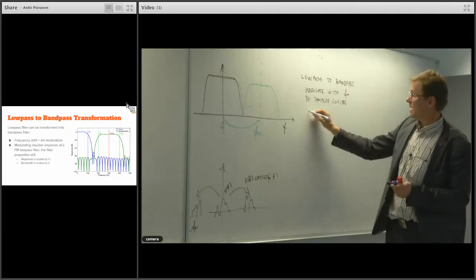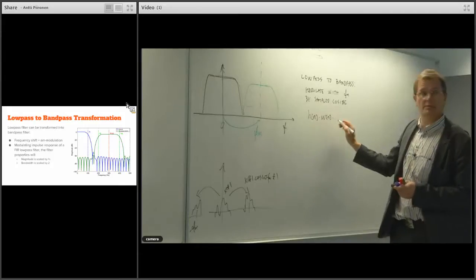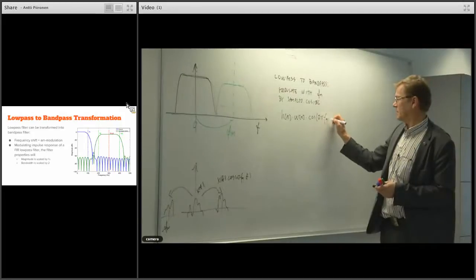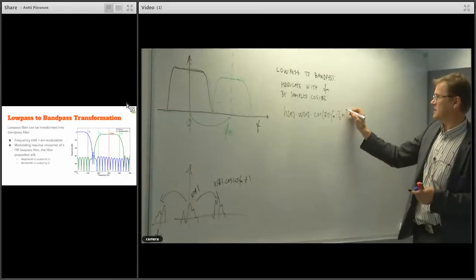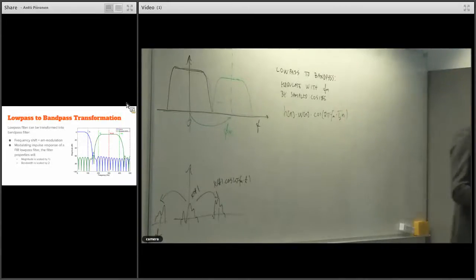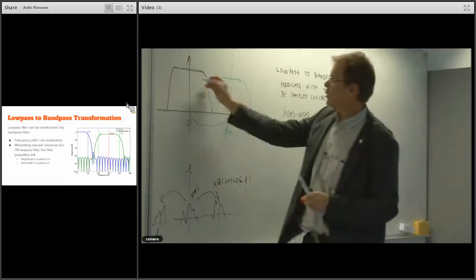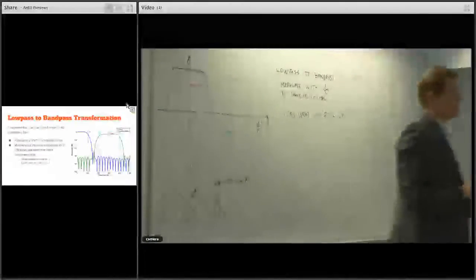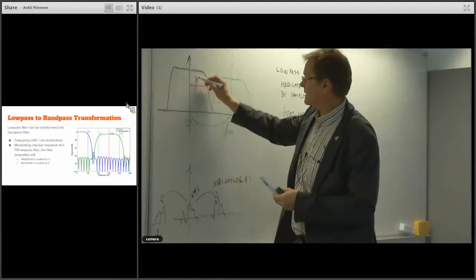Okay, so we have h of n times the window shape times cosine 2 pi fm times t s times n. Okay, that's the whole thing. Just with one reminder about bandwidth. For a low-pass filter, this is the bandwidth. It's the physical frequencies. We don't think of it as too complex on this one. So the low-pass filter bandwidth is here.